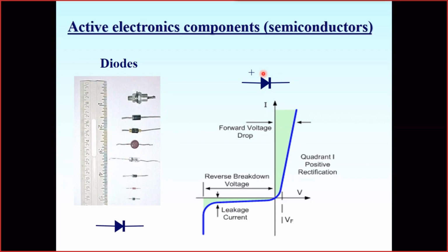That's why at high frequencies the leakage current of the diode increases, because it actually flows not through the PN junction itself, but through the capacity of the PN junction. We have to remember that at very high frequencies our diodes may work poorly, because they no longer provide this one-direction transmission. For a very high frequency, they may even become bidirectional.